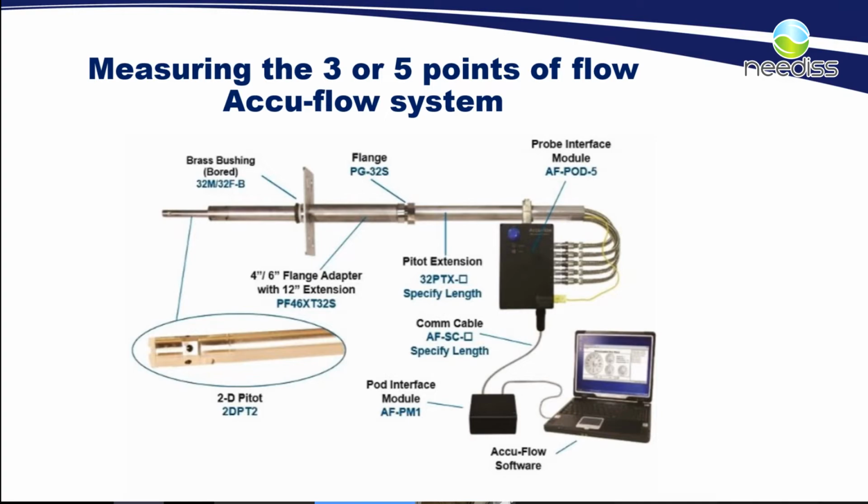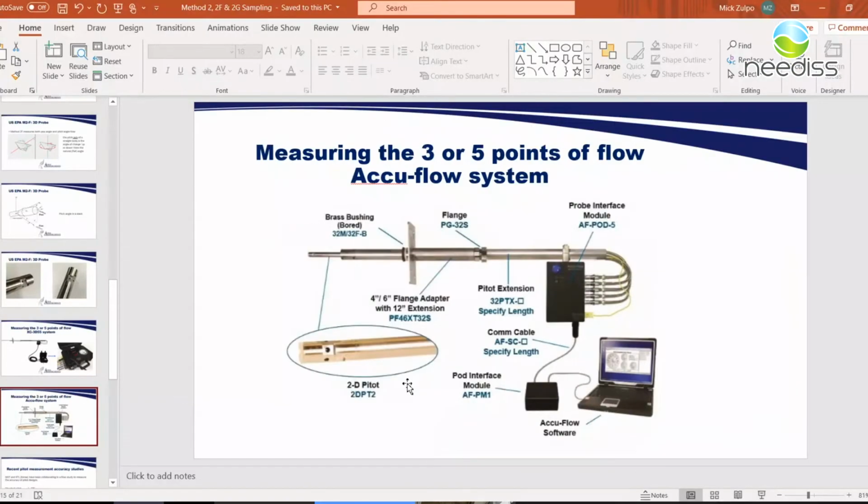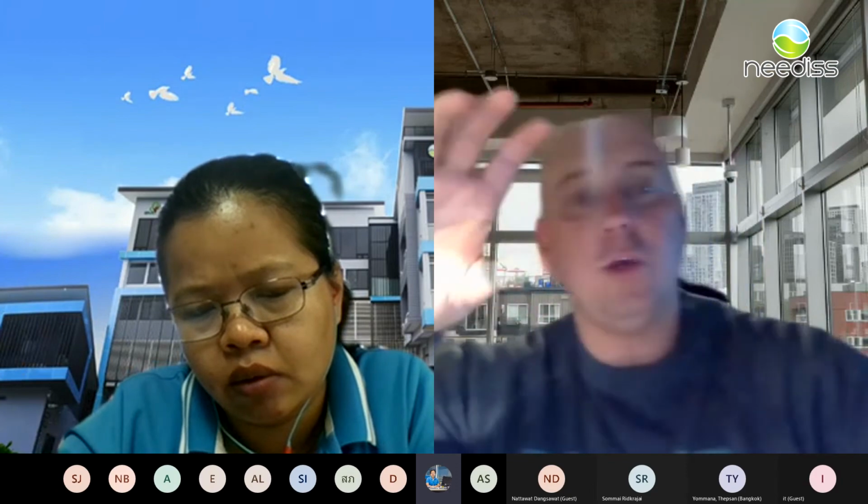So that means with the XC 3D 55 with the manual console, we must know the angle when we are measuring the different degree of the angle, right? Correct. So typically what you would do is you would have a manual inclinometer on the back of the probe, like a device that shows you the angle, and the operator of the probe would turn the probe until on the console here you can read.